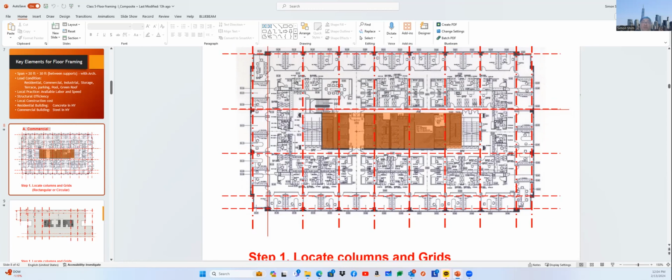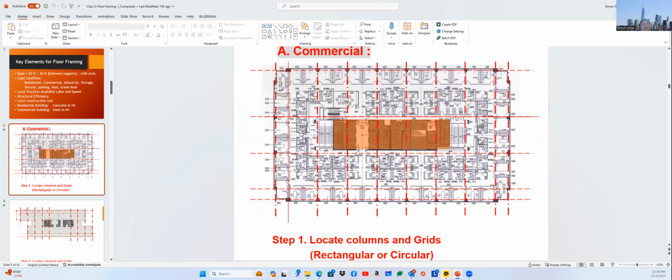So obviously, let me zoom out. This layout explains everything you're going to do in your final project. You need to come up with geometry, footprints, right? Building floor layout. I think you guys already discussed geometry. I don't want to give too much restriction. If you choose a site, you come up with a floor plate dimension. It could be square or rectangular or circular, but rectangular or square is relatively easy to create. But the column layout you need to discuss among your team. Initially, place the columns based upon your column grid.